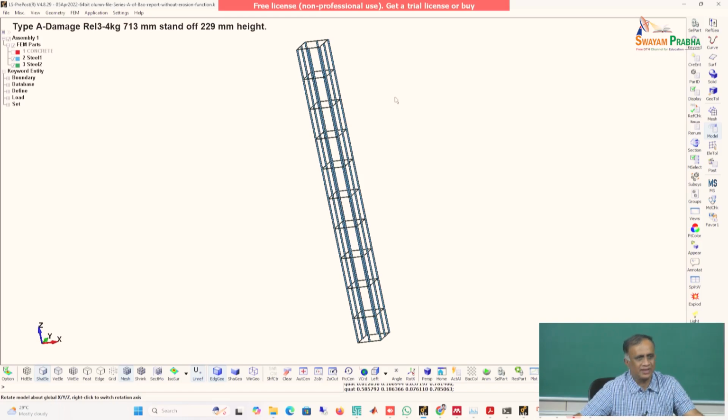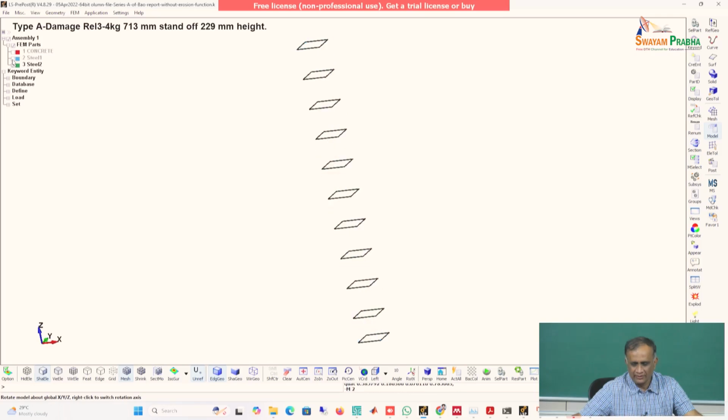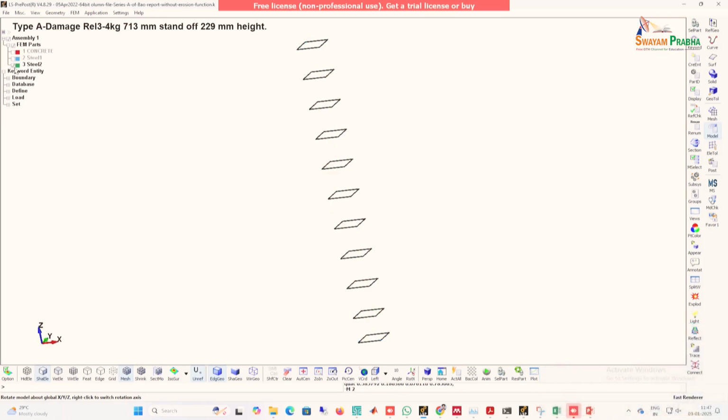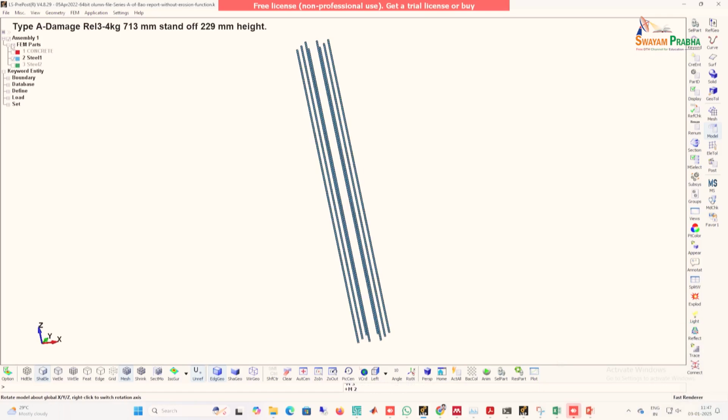Here you're using actual finite elements. So you have to simulate each of these, as I've used beam for some reason, but these are all axially loaded elements, and you have to simulate each one of them. And so it starts with your meshing. Then if you take out the steel 1, steel 2, so you have to create all these. So that complexities are there.